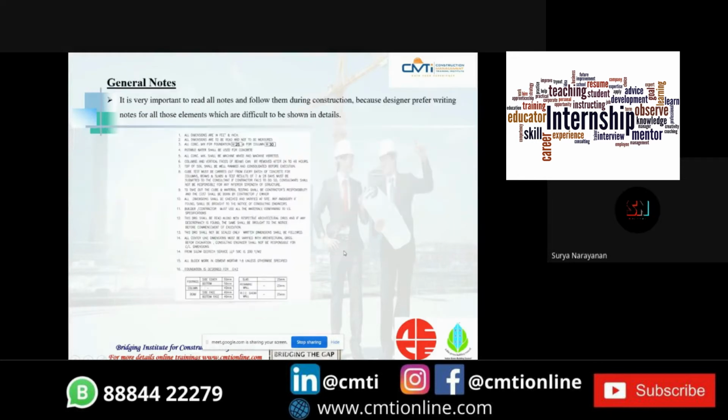So moving on with the next slide, it is about notes. Once the title block is read, we should check with the notes because all the details cannot be explained in a plan. So they give you detailed explanations in the notes, where we get information such as dimensions, whether it should be read as per the scale or not, and what units are being used in the plans, like meters or feet, etc. And what are the mix designs used for the foundations and columns, like M25 or M30.